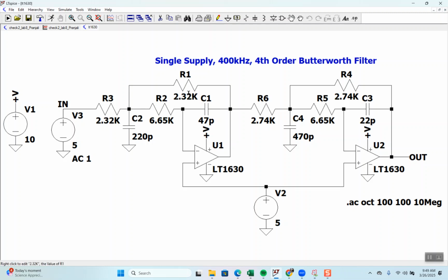Notice one, two, three resistors, two capacitors. Okay, so there's some more parts, right? But notice how the input is coming in. It's coming in on the inverting side. It still has this positive feedback, and so does this, right?